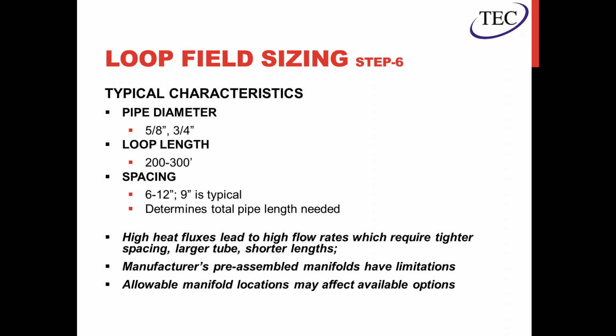And another thing to consider with the manifolds is your pressure drop coming back through that header. Manufacturers' pre-assembled manifolds are all tabulated, so you can pull those when you're doing the design. But if the contractor is going to be installing hand-built copper manifolds, that's something you want to make sure is accounted for as well.